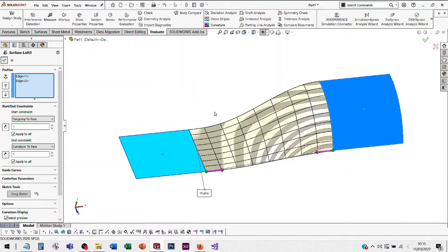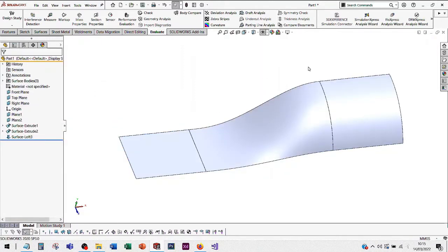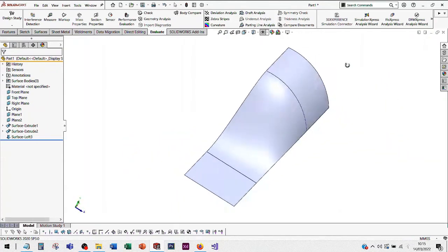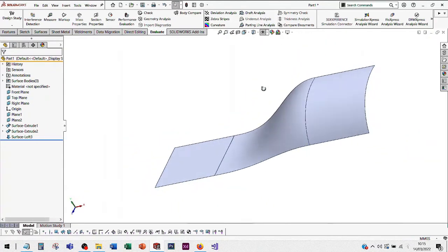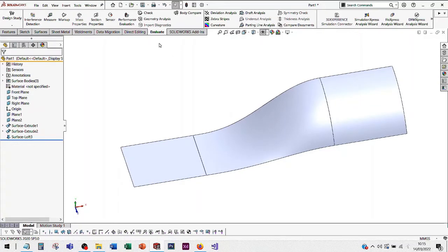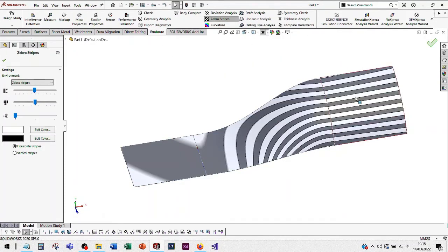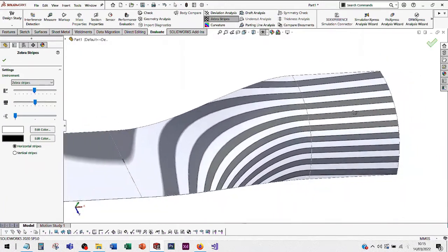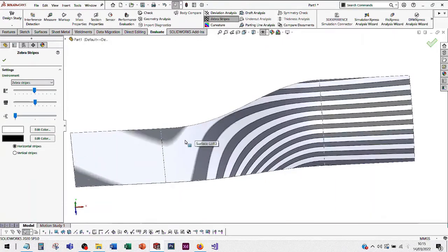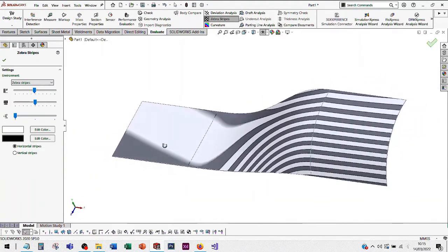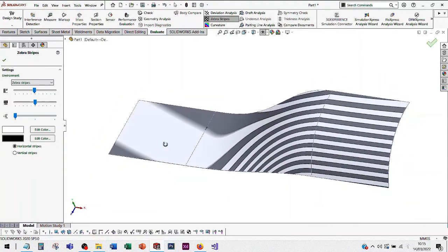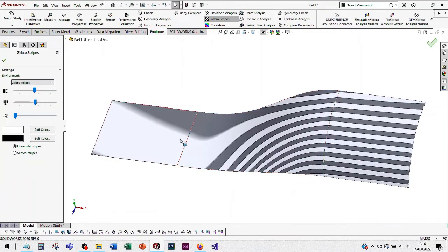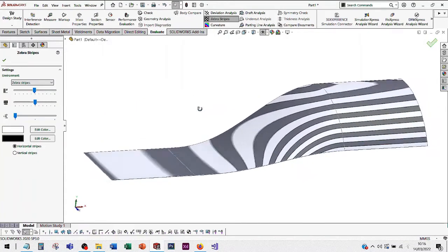Let's click OK, have a closer look, and on the face of it, it looks almost similar to what we just had, but as you will now see, after we look at applying the zebra stripes, we can see a clean transition between the curved surface, which has certainly improved, and a much better transition between the surface loft and planar surface.